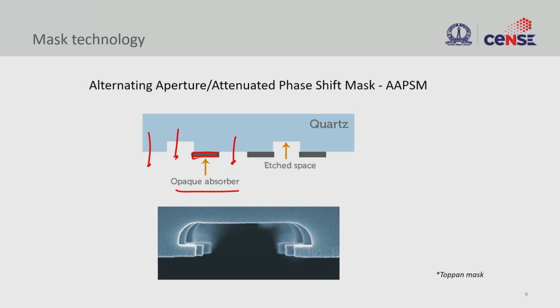What we are trying to achieve here is you get the light modulation by using phase shift here, and in this case you are using just the power difference between these two. So a complex mask could be built by using this technology to achieve better resolution. The only downside in this kind of advanced mask is the circuit design itself. When you have structures from different devices coming close to each other, managing those phase shifts and the absorption is going to be a challenge.